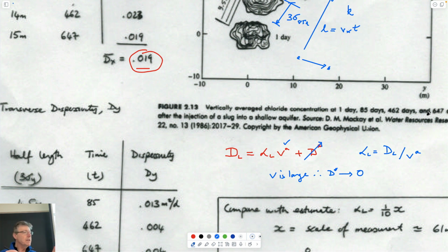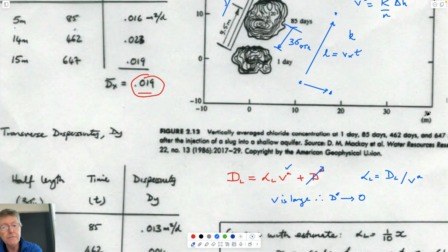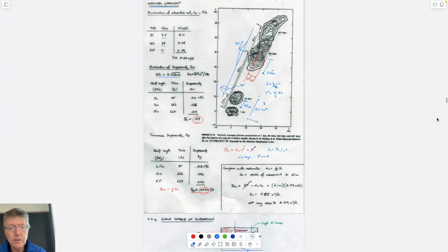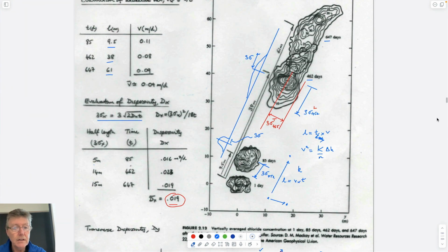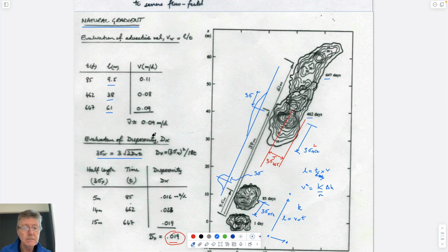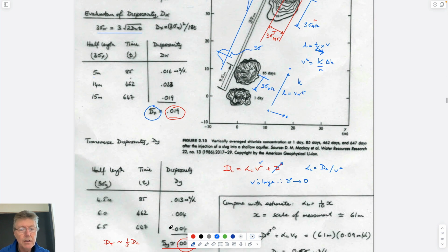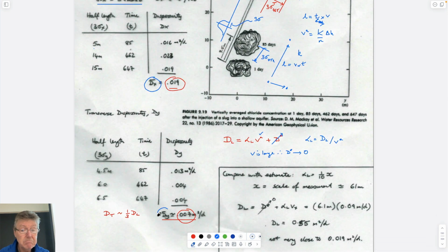Know what the solution is in terms of the bell curve, the Gaussian distribution. 3 standard deviations is just the length of the plume from its center of mass, either longitudinally as it travels downwind or transverse as it travels downwind. And we can use those values to represent the magnitudes. We can solve for the value of what we call either d sub L, or d sub t.